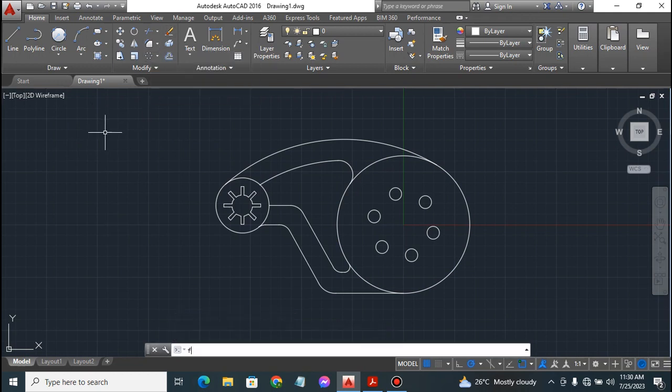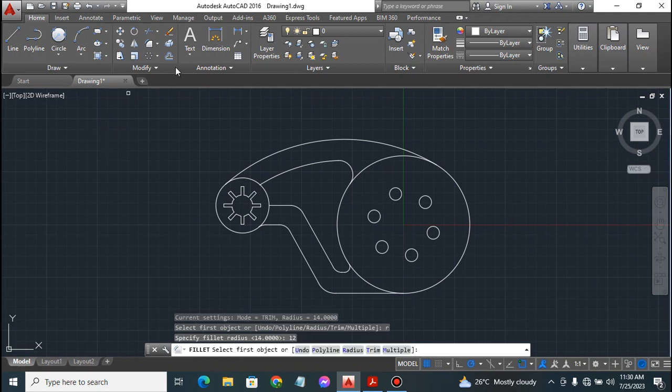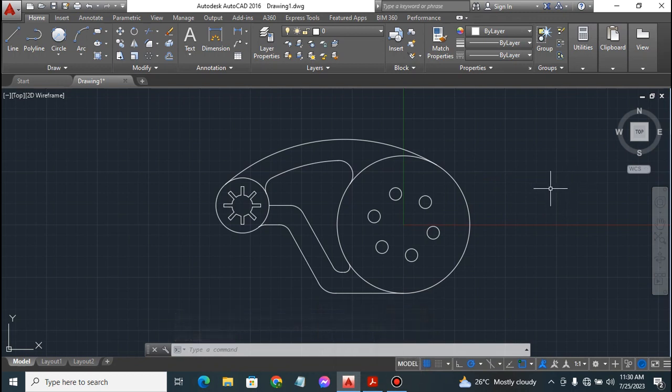Next up, to the left we have a fillet radius of 12 millimeters. Using the same approach, type in fillet in the command line, press enter, type in R for radius, press enter, type in the fillet radius, which is 12, press enter on the keyboard. Now we click on the lines that form this straight edge, click on the two lines. Right, so that is it. That's what we need. I believe we've done justice to this drawing in total. Let's do some comparisons by looking at the one we have in our PDF document and the one that we just finished drawing.